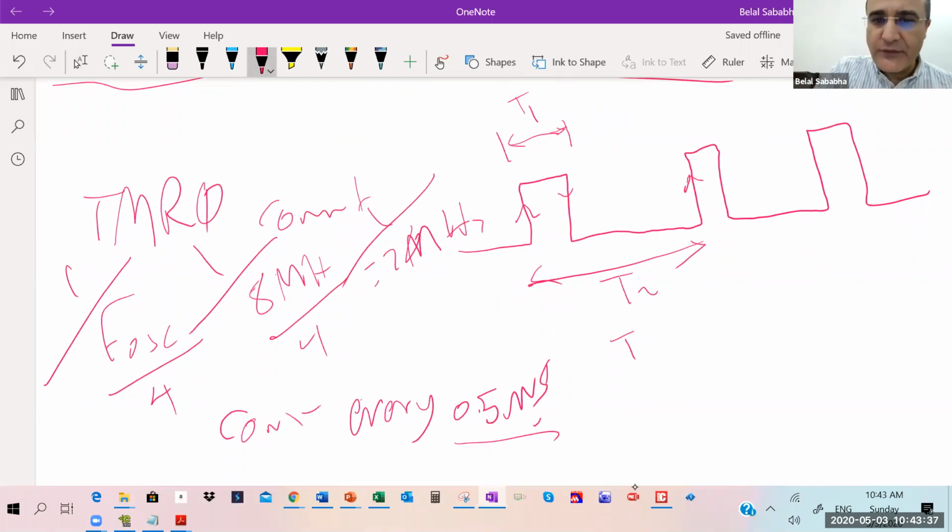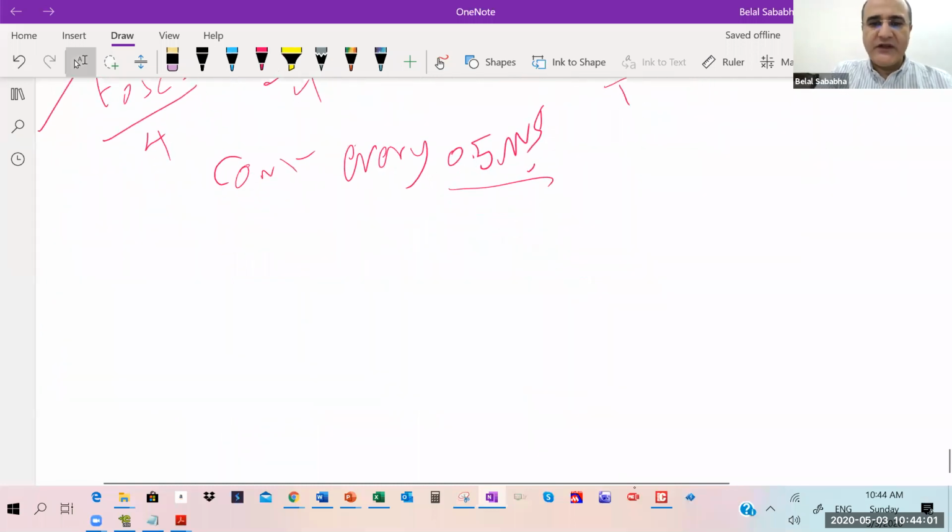You can use the interrupts to latch or copy the value of the timer when a rising edge happens, and copy it when a falling edge happens, and keep the timer 0 overflow interrupt tracking how many overflows happen before the next edge comes. Let me give you an example.